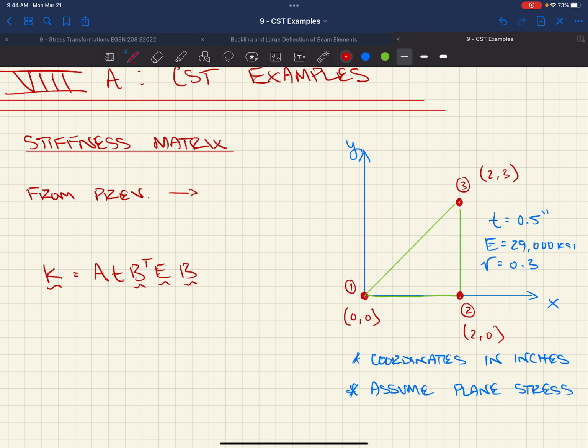So you have this very, very small stiffness, and then all of a sudden, boom, you get a displacement. Not a real displacement, but a displacement. In that case it was 7 light years out there. It also rotated a million times. So you can get an answer. It might not be a good answer, but you can get an answer, which comes back to validation. There's error in just the numerical operations of our software systems.